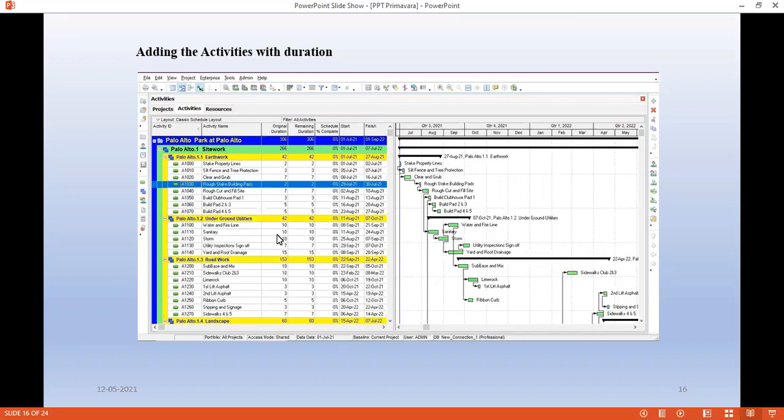Here we are going to add only activities, specifying the duration and giving the relationships. And this part is nothing but the Gantt chart, or you can say the bar area. As per the relationship link lines, you can use this relationship link. After giving the link, it will specify the original duration in terms of number of days, so it is going to calculate here.